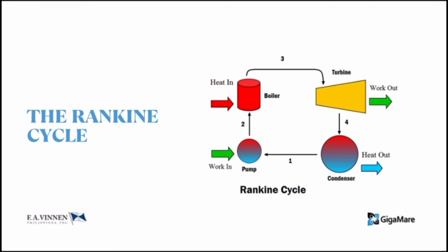Aside from the principle of evaporation and condensation in the boiler, I would also like to incorporate the Rankine cycle that is happening inside the turbine. The superheated steam generated by the boiler is used by the turbine, and this superheated steam expands through the series of turbines and generates electricity through its output shaft.